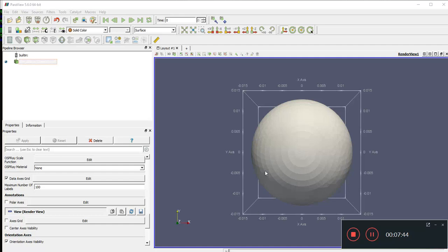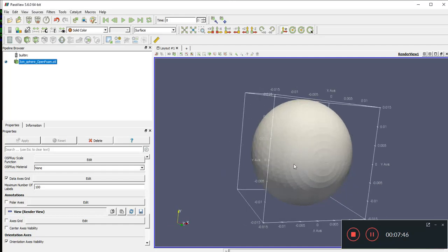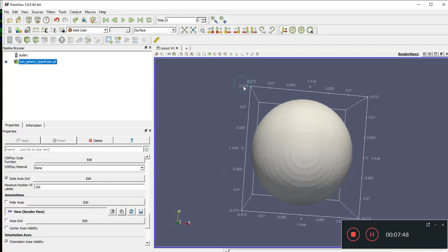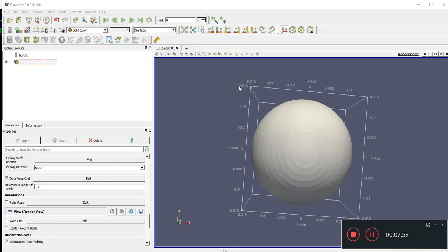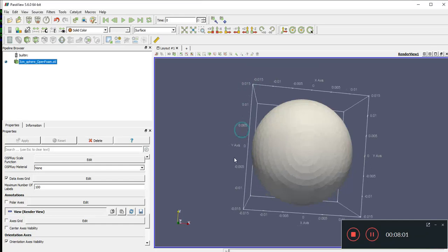Yeah, you should be able to see it. So remember, OpenFOAM likes to interpret all these numbers as meters. So this is 0.015 meters. While FreeCAD likes to interpret all these numbers as mm. So our STL file is pretty okay, no issue with that.